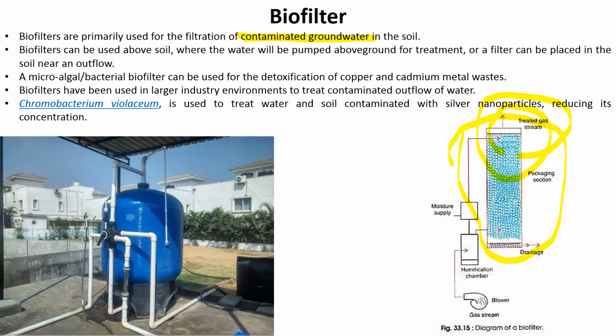So you can use it in an above soil process. You can pump the water above ground. You can place an outlet. You can converge water from different resources, from underwater tables, and then use biofilters to treat your contaminated groundwater. So it can be used ex situ, it can be used in situ. It is a very common technique used for treating contaminated groundwater.